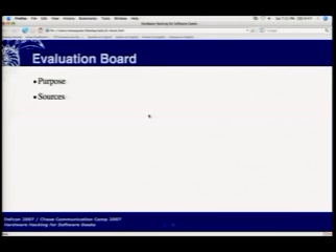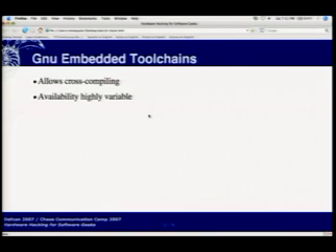Let's say you just take a chip name and type in prototype or evaluation board, you're going to get tons of them. Now, you can build firmware for this using standard GNU tools like GCC and everything else that you'll need. Basically, you have to compile a cross-compiler, which means you delve into the specifics of all the GCC compilation settings and pick your architecture to compile cross-compiled binaries for.